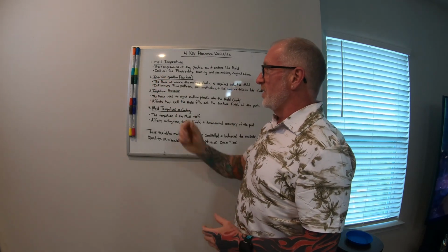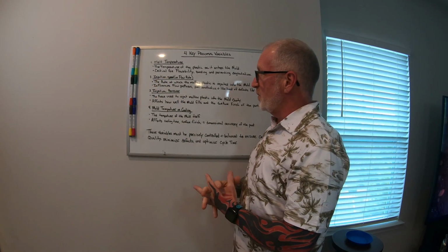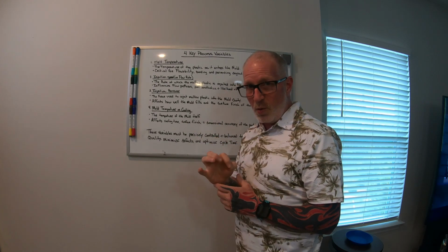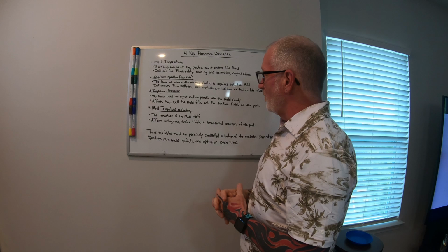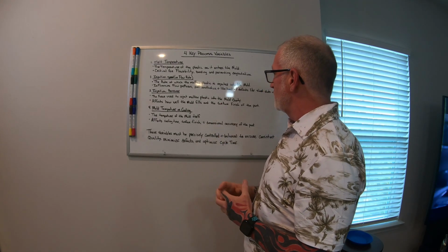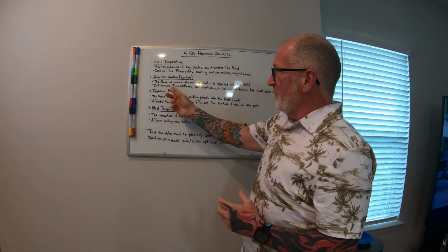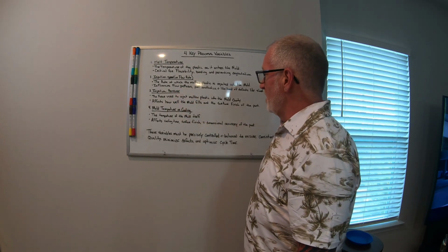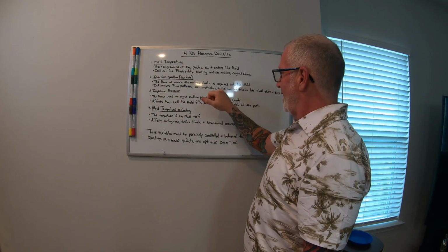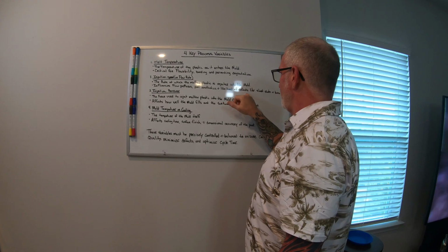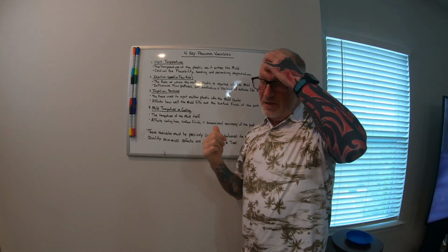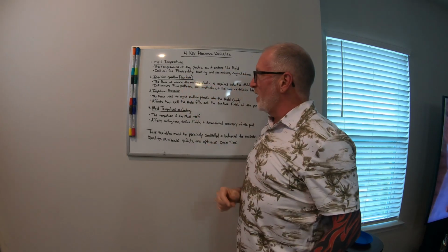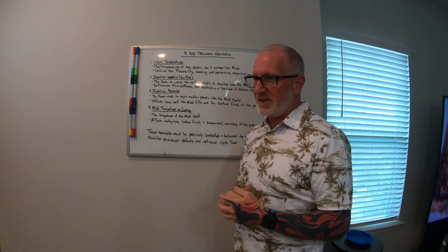The next thing you'd want to do is go to the injection speed or flow rate, okay? So injection rate is the rate at which the molten plastic is injected into the mold. It influences flow patterns, viscosity, and likelihood of defects like short shots or burn marks, okay? So on this one, let's say your flow rate's the same every single time.